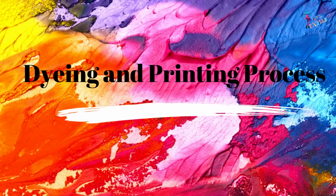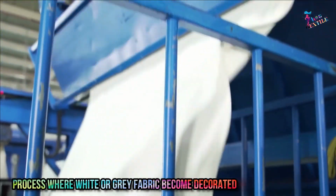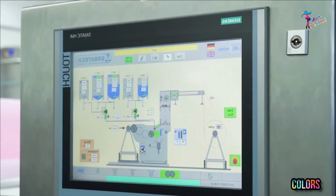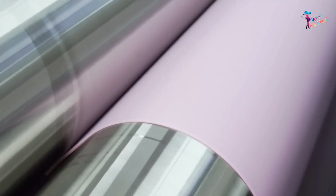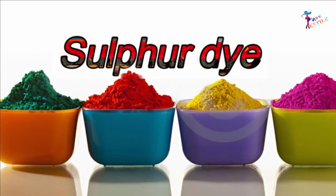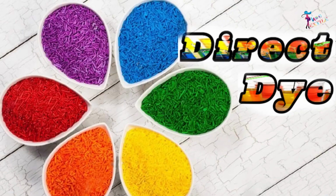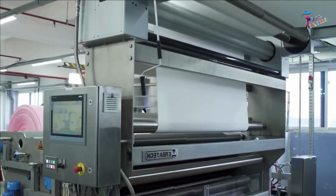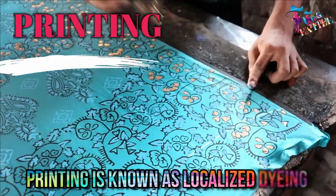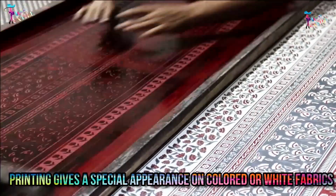Dyeing and printing process. Dyeing is the main process where white or gray fabric becomes decorated by different colors. Dyeing of textile substrate is performed using any of the dye stuff including reactive, direct, sulfur, vat, pigment, acid, and disperse depending upon the dye fiber system compatibility. Printing is known as localized dyeing. Printing gives a spatial appearance on colored or white fabrics.